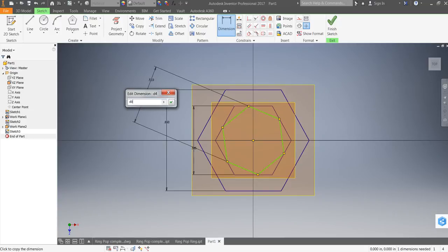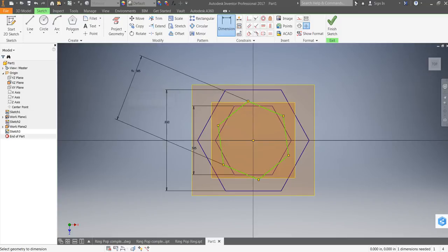If you notice up here, there's a reference point on each one of these. So it's just like putting in a variable into a math equation. The nice thing with this is that if I ever change this bottom dimension, my top dimension is going to change too. Now if you notice here, I put this in at an angle so it's not lined up with the others, just to kind of show how I'm locking that in, because notice it's still green. When I put that horizontal constraint in, notice it spins it back around.